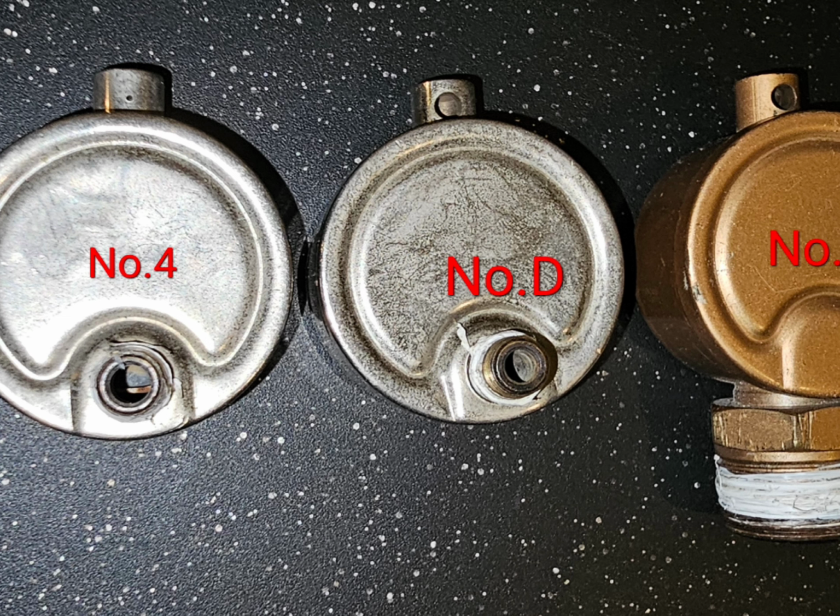I'll tell you one thing. The wider the radiator, the bigger the depth of the radiator, the better the heat that it actually holds. So if you have an 8-inch steel convector, it's going to hold heat a lot better than a 2-inch steel convector or a 6-inch steel convector. A 2-inch steel convector will have 2 tubes, steam or water tubes running through it. A 6-inch steel convector will have 3 tubes running through it. An 8-inch steel convector will have 4 tubes. And they even got some that are 10 inches deep, if I'm not mistaken. I think they have 5 tubes. But those are very rare.